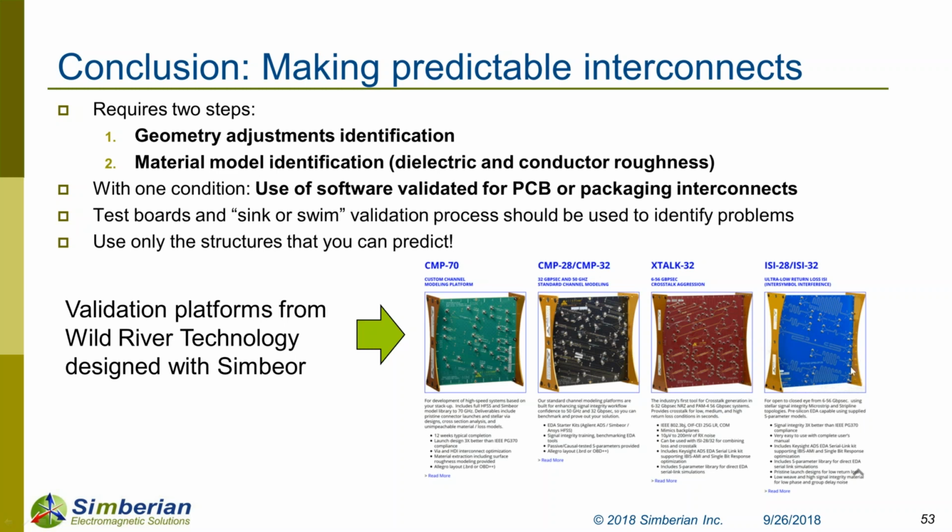Stack up, SL material selection, roughness definitions, and signal launch sensitivity. Basically, all of these materials are available in the app note section of the Simbeor homepage. When it comes to stack ups, we used 2-ply core and prepreg in order to mitigate fiber weave effect. Roughness definition, well, there is no roughness definition. We just know it's HVLP copper. And again, keep in mind, there's a difference between starting roughness and the fabricated roughness, because the vendors do some micro etching, oxidation, bond treatment. Everyone does it differently. So you have to identify the roughness.